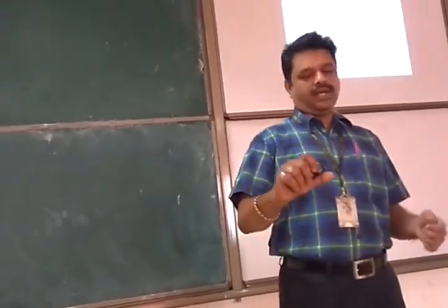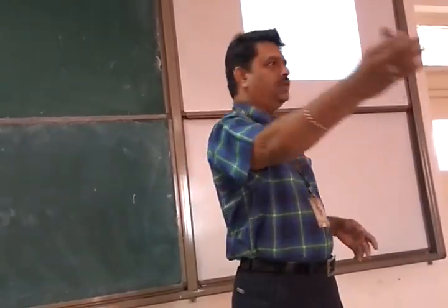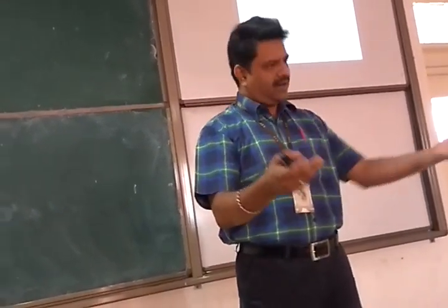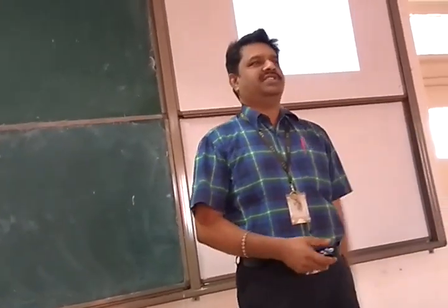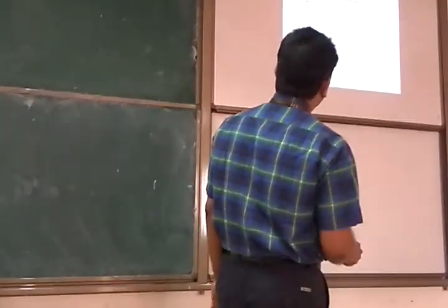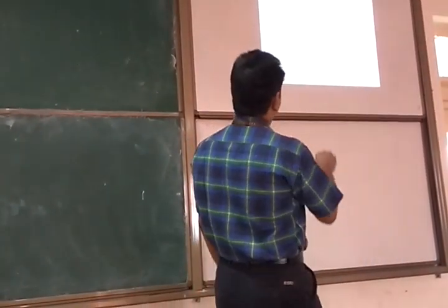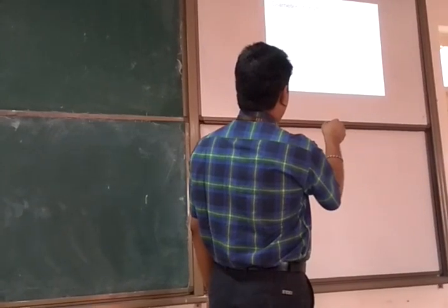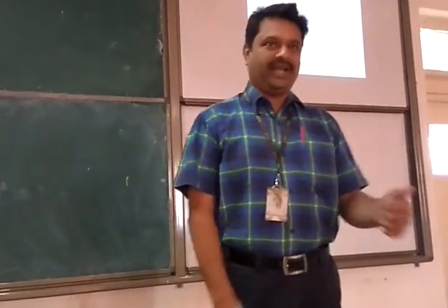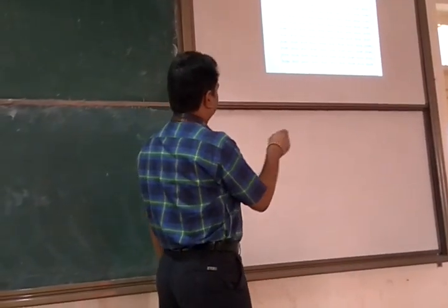We take a rod, give a micrometer or a vernier caliper, and ask individual students to make measurements. Same shaft, same instrument, different observer, or even one observer, we take 100 different measurements. We will typically get something like this. This is actually typically, I have made 100 measurements myself in the cabin. Okay. Took a rod and measured the diameters. So something like that we get.